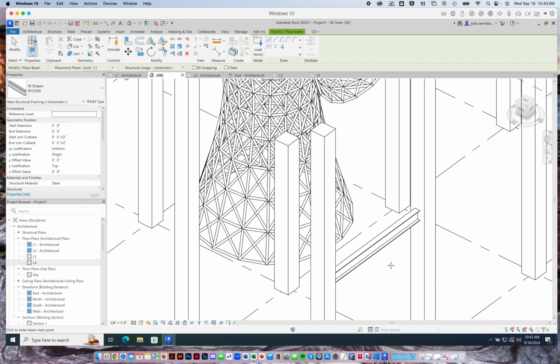But anyway, right, so you can see that we have concrete slab poured on a corrugated metal deck. That metal deck is spanning between beams, right? And then we have systems running underneath those beams, right? Air, plenums, ductwork. We have raceways with data and electrical, and then conduit running out. We have drop-downs for projectors, lights, power, etc. Right? So a lot going on in between in that sandwich.